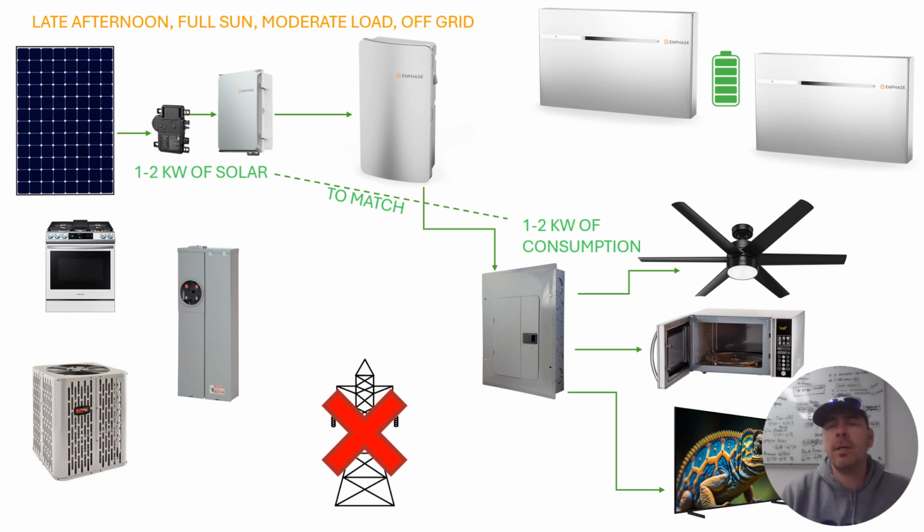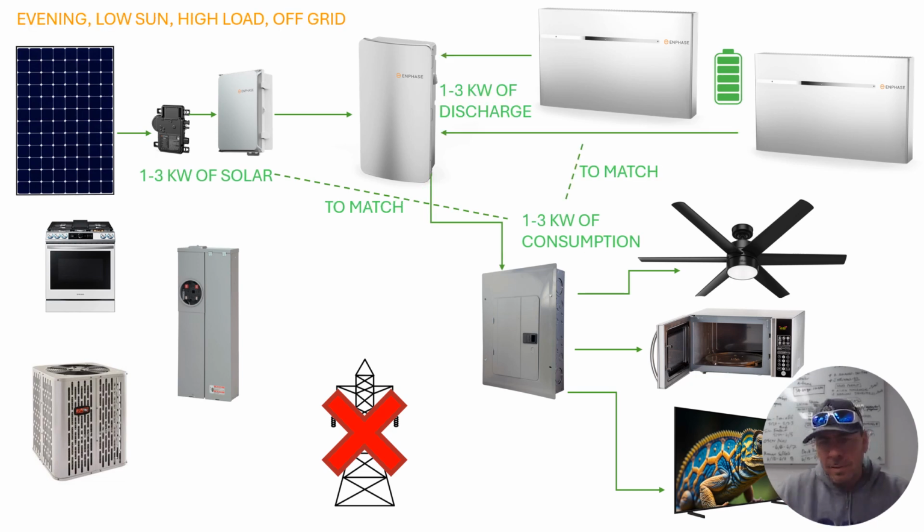and in a safe way possible too, because it doesn't want to have a bunch of power coming from both the inverters at the same, more power that's coming from the solar, sorry. It doesn't want more power coming from the solar than the loads can handle if the battery is full, because it has nowhere to send the power. So it has to modulate it for safety purposes to make sure that the power has somewhere to go. Okay, hope that makes sense. It can be a bit confusing, but let's look at the next slide anyway and see how it works a little bit in the evening time.